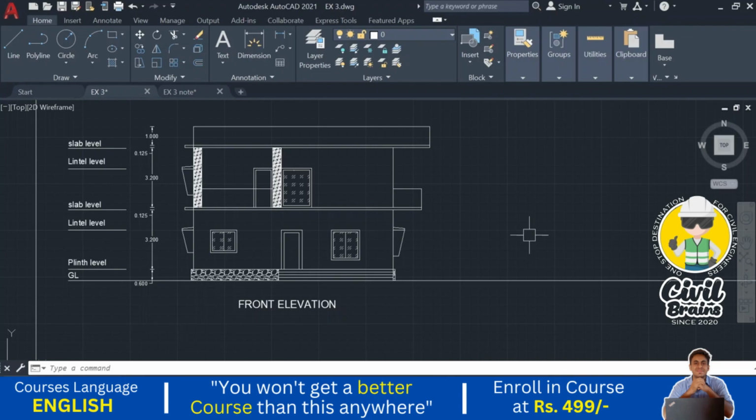In the working drawings, in most cases we are not providing any aesthetic things. We only provide the levels, so that at the time of execution they can understand the levels, and we also provide the structural components. Like if there is a slope slab, then we need to show the slope of the slope slab.